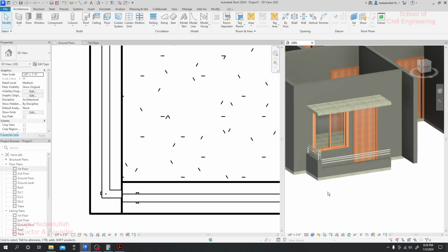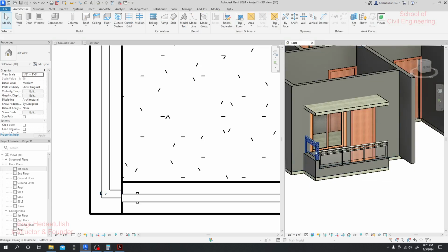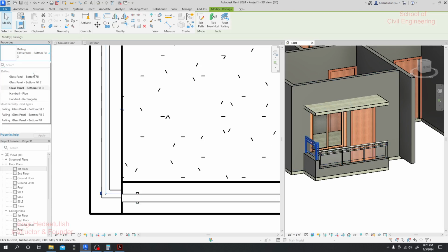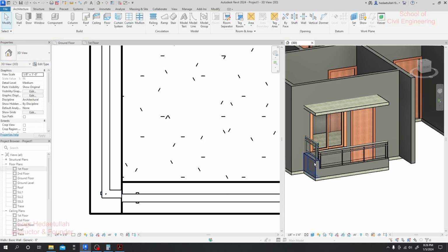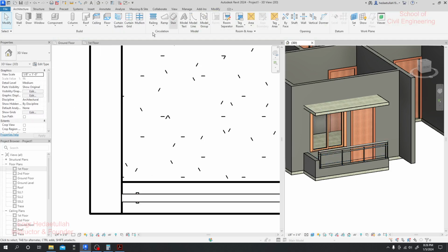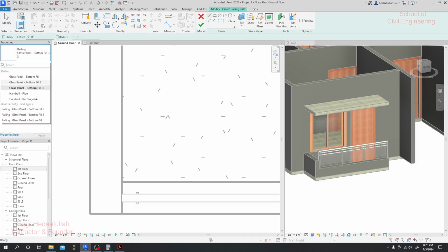So I have to select that one. I'll change that with fillet 2, because when we changed it, this one has been changed to 3, so I'll delete that one again, and I'll just go here for sketch path, close, click here, go for sketch path, and I'll take 2. Our base height will be 2 feet.